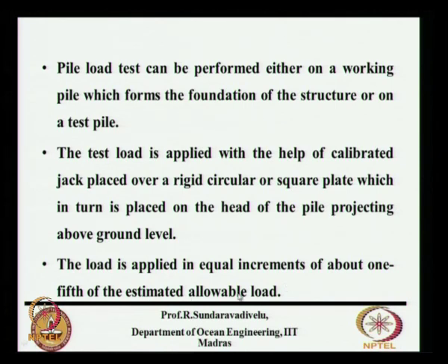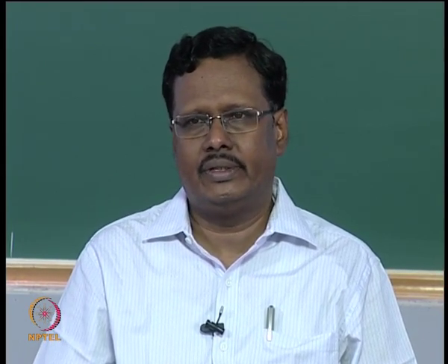The point here is you apply a load of 100 tons, do not take the reading and go to the next increment; you keep it for some time for it to stabilize. So you have to load it, then unload it also. What we record is the load from the jack, and also you have to record the settlements.